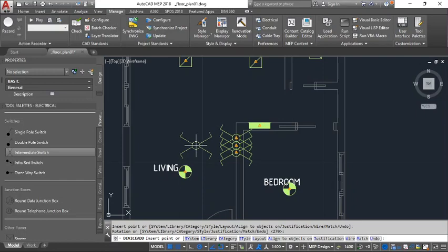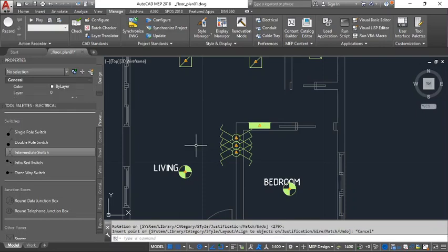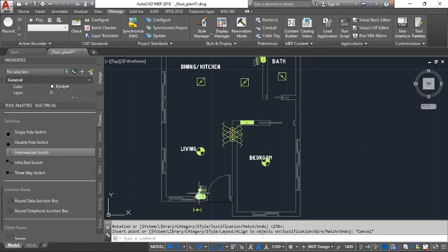Basically it has three terminals. Two-way has two terminals. Same thing, four-way should have four connection points. If you want three or more switching locations, then you need four-way switches in between. They are always in between the three-way switches if you are doing the circuitry. So you start from three-way, connect, but the four-way switches have to be in between.